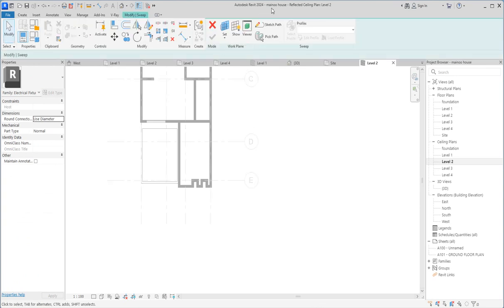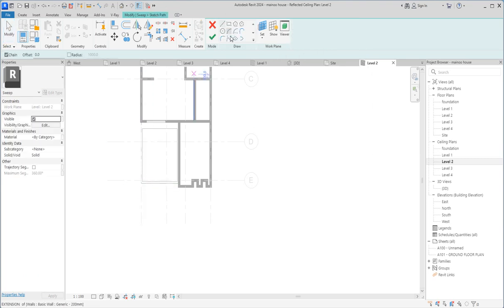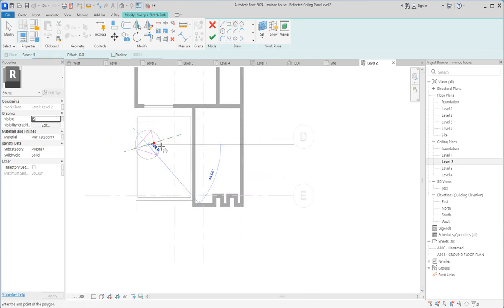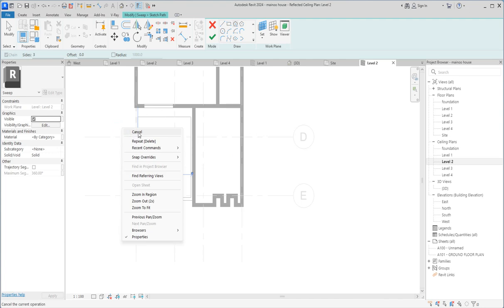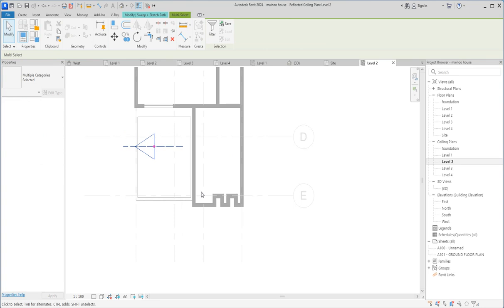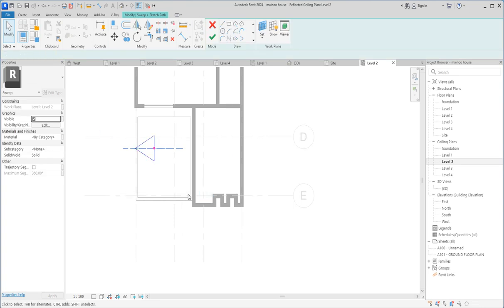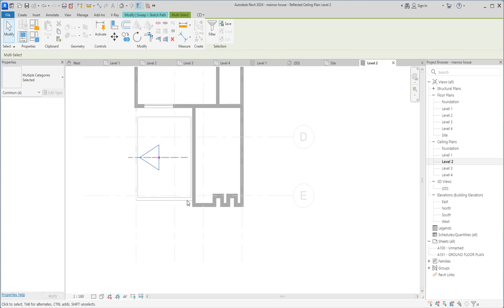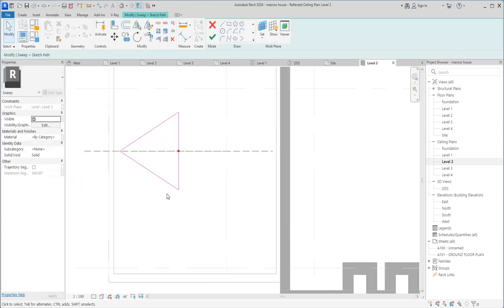sweep blend experiment. So I'm selecting this, I'm going to pick a path that I want it to follow. So from the path now I will select this and say okay, I'm taking a polygon of what three side is okay for me. Press enter. So from there you select this kind of pattern that I want, and I want to use it absolutely. So I selected this pattern, you can shift it. So save the pattern, save it that way.